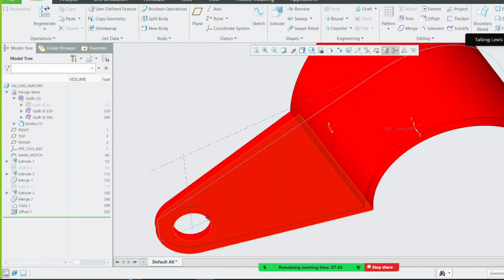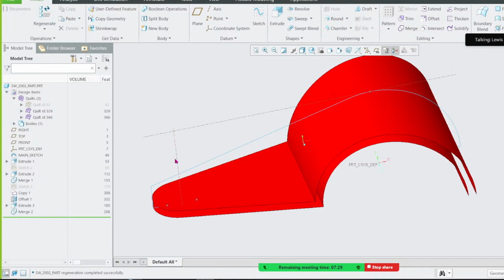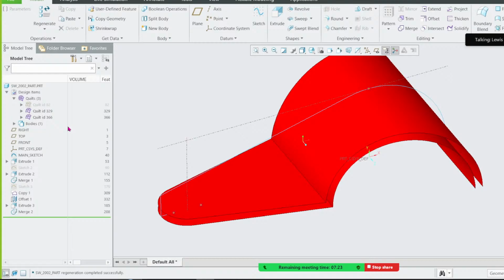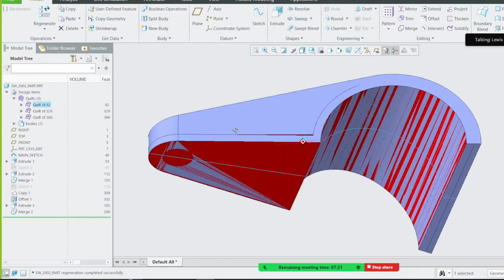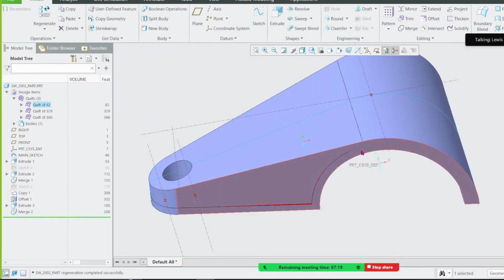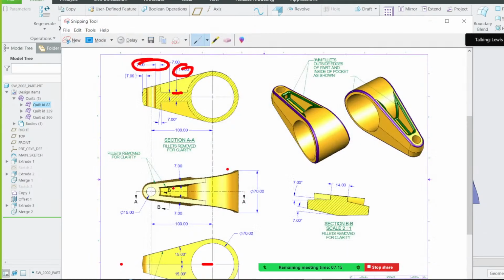You see something here, you're getting this hole. Okay, if you don't want to get this hole, what do you do? Just take the hole like that, move the hole. It has disappeared. That is in case you don't want your surface to have a hole there. Therefore, now we have this surface here. Now we need to define a sketch that is 7 mm away.